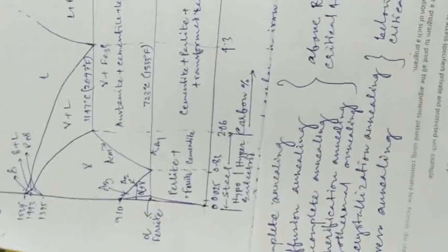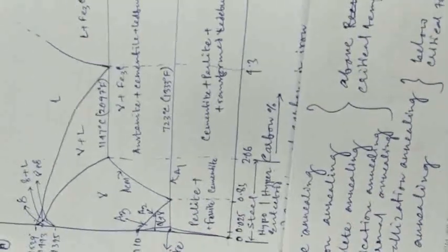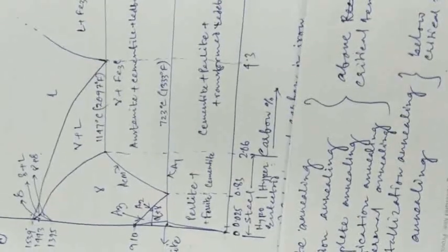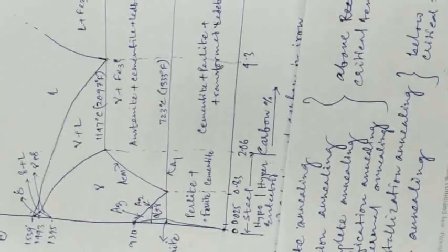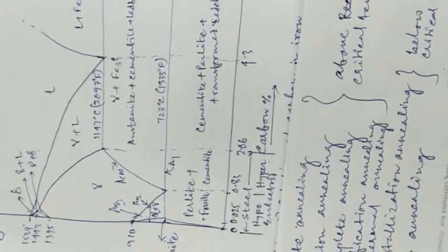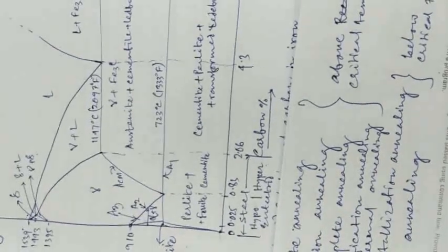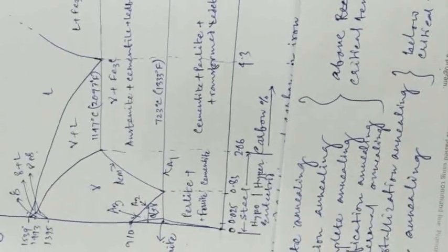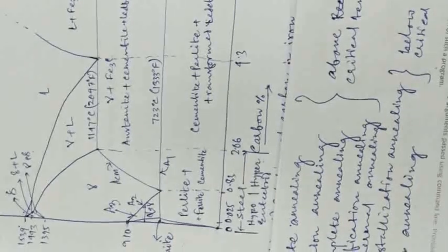Cold extrusion and cold upsetting parts of low carbon steel or medium carbon steel sometimes use spheroidizing annealing. In order to eliminate work hardening, recrystallization annealing can be used. In order to eliminate the internal stress caused by various processes, stress annealing can be used.